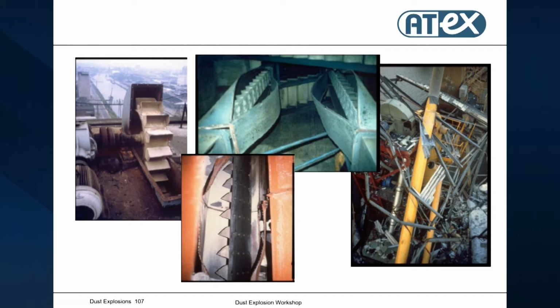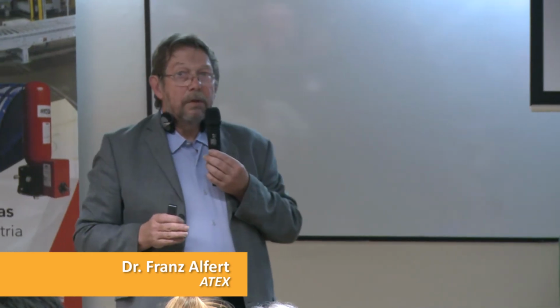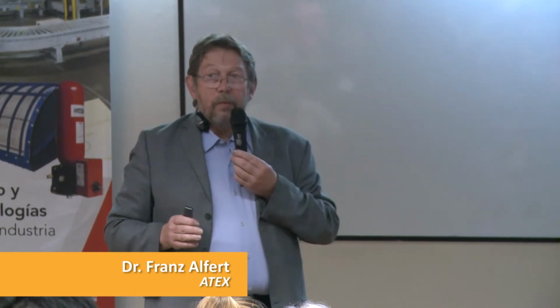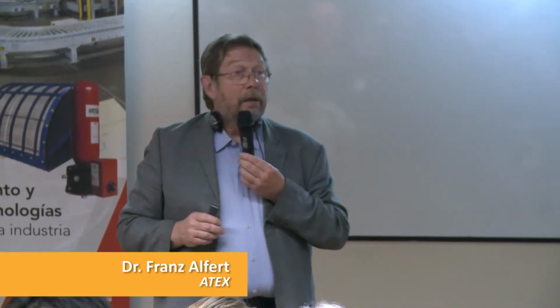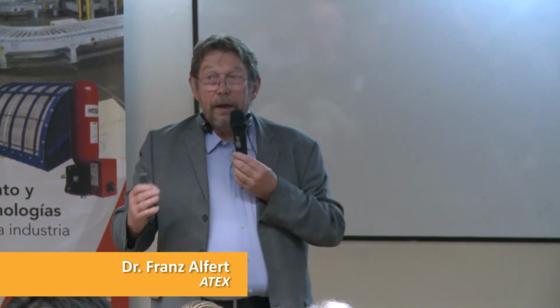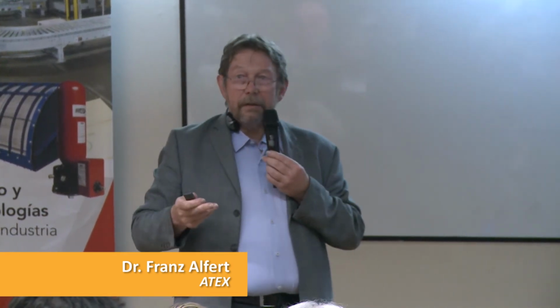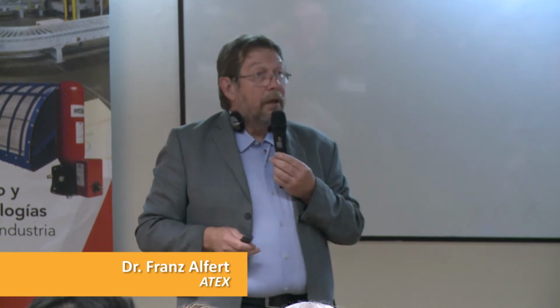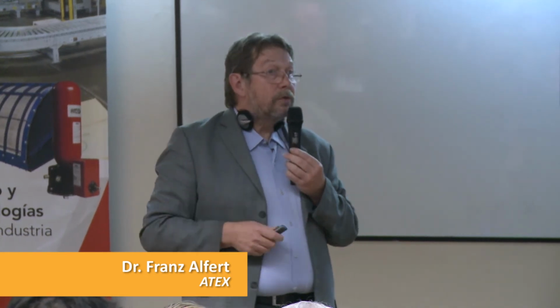Elevator explosion, just a few words on that, because we have frequent elevator explosions which very often turn into secondary explosions. The elevator opens, flames come out and go into an area where you have a lot of dust. You do not have explosion isolation, so the flames propagate through the elevator into the silos, and you get these huge silo explosions.